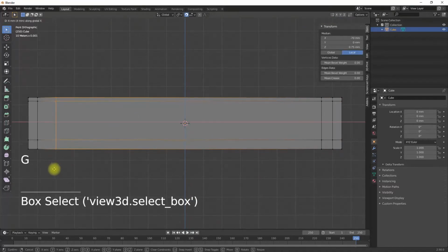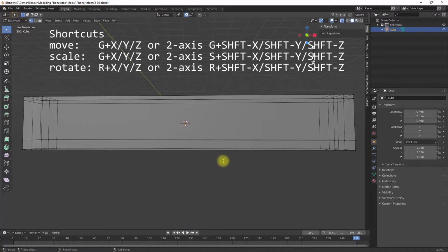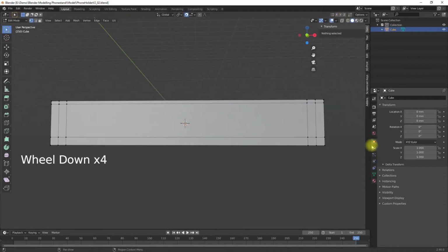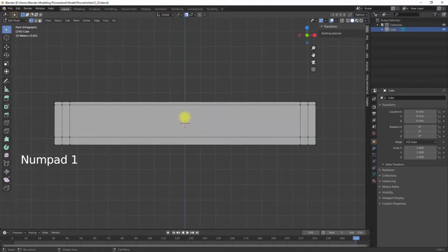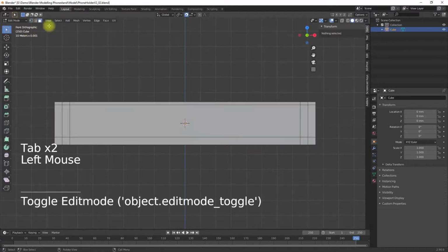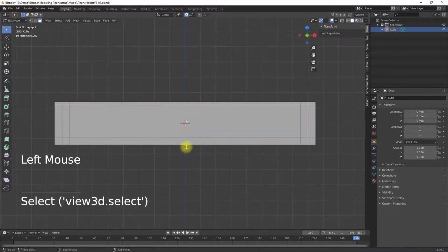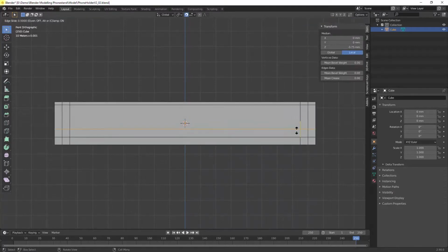Using the Ctrl key while moving the loop cuts gives me the possibility to move exactly one grid dimension up or down or left or right, depending on the direction I pre-selected. Another important rule for Blender precision modeling is to pre-select the direction if you move, extrude, scale or rotate any element. Use the shortcut keys to restrict the direction you're going to use for your current operation.